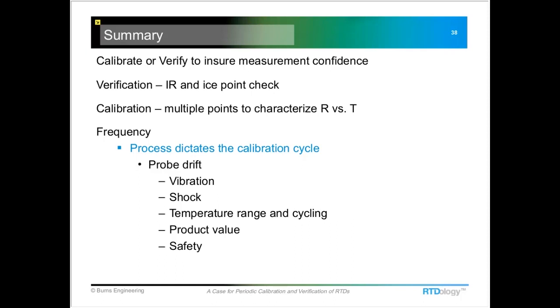One thing I did not mention earlier is that when you do a calibration, there's really no need to do it over the full temperature range capability of that probe. You should keep that range as small as possible to cover just what that probe is being asked to do. So if you're measuring 100 degrees C, don't do minus 196 to 500 C. That puts the probe through a lot more stress and strain, and you're going to get some wider tolerance band numbers for that kind of a calibration. So you might want to just do 0, 50, and 100 degrees C.